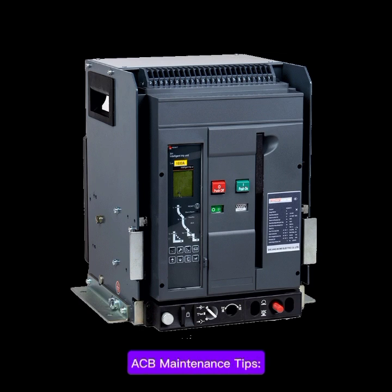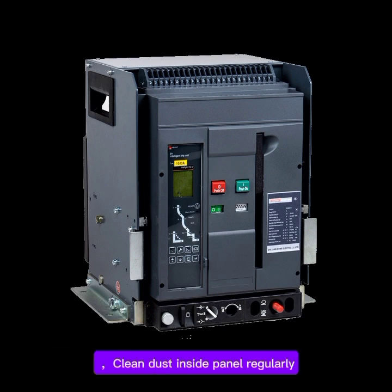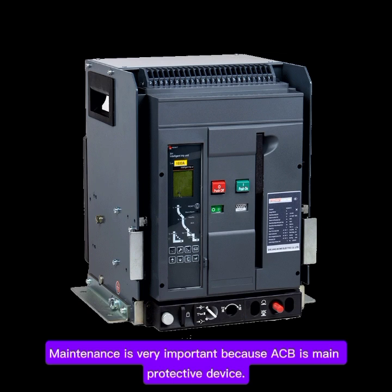ACB maintenance tips. To increase ACB life, follow these maintenance steps. Clean dust inside panel regularly. Check contact condition. Tighten busbar connections. Check spring charging motor. Test trip unit settings. Perform insulation resistance test, Megger test. Perform breaker operation test. Check arc chute for carbon deposits. Maintenance is very important because ACB is main protective device.